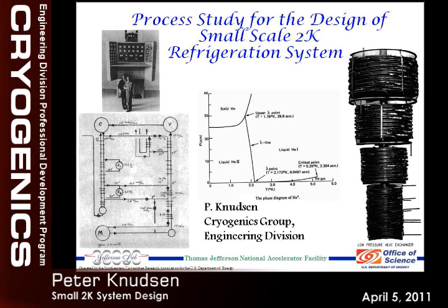And this is the heat exchanger. Basically in the center of it, this is about 7 feet tall. It consists of 4 sections, and it's basically a tube that's wrapped around in a loop, alternating the tube passes go from in to out, and then from out to in, alternating back and forth. And it's a tube with a fin on it.